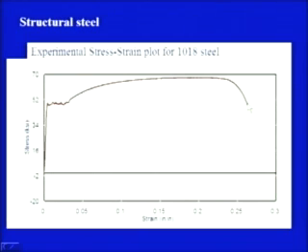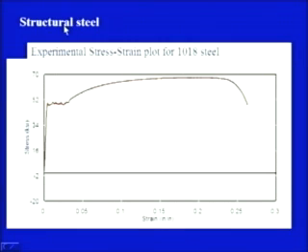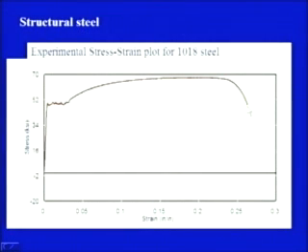Now, since we are discussing the previous figure for the structural steel, and this figure is also structural steel but with a different carbon composition. Mild steel or structural steel is always termed a ductile material. Ductility is the property of a material through which it can extend up to a certain limit without failure. So we can clearly distinguish the elastic and plastic regions for the ductile material, and whenever there is a rupture or failure in a ductile material, we get almost the shape of a cup and cone structure.